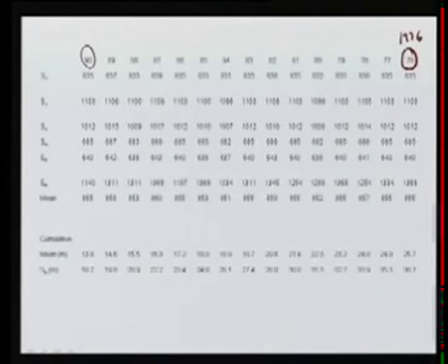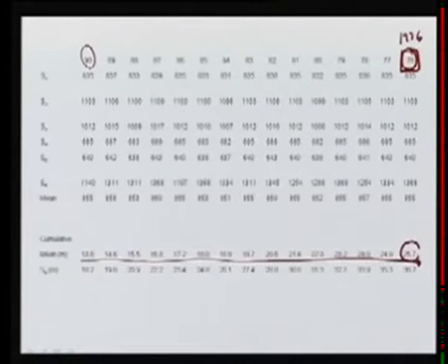and going up to the last year for which we have record, which is 1976. So this cumulative mean reaches up to 25.7, which indicates that in this 30 years period we have total of about 25.7 meters of rainfall as the mean of the 5 surrounding stations.